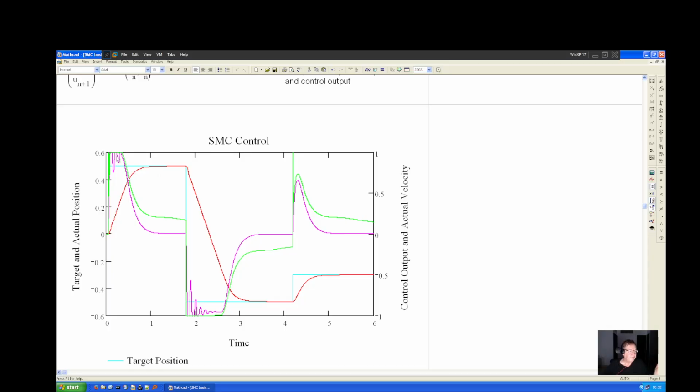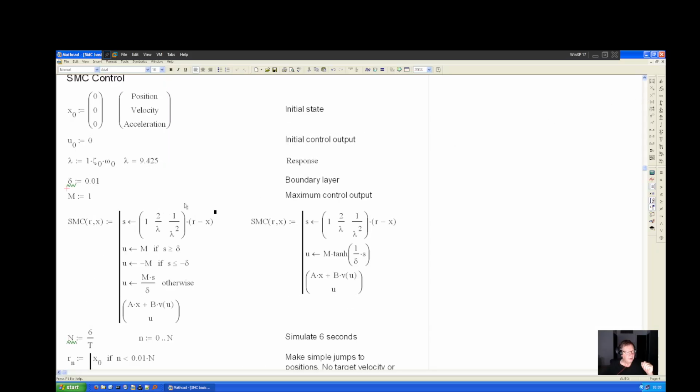Because I've got a second order system that's underdamped, when the output goes into saturation, you're basically running in open loop mode and you're not really controlling the oscillations. So I'm seeing oscillations here where if I were to plot the velocity above 1 meter per second, you would see it actually go above 1 meter per second. But then you can see as it approaches my set point that it ramps down nicely without overshooting. And that's because of these parameters that I chose right here.